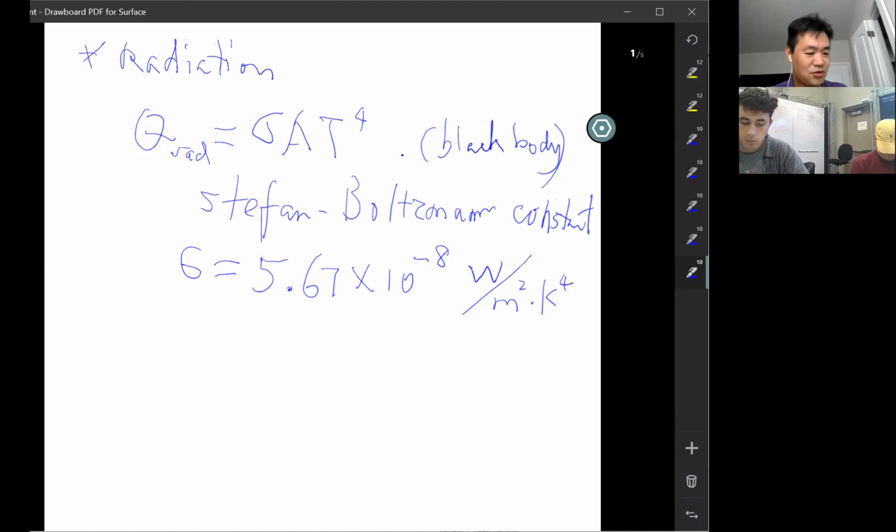But in homework problems and test problems, they always give you Celsius. If the problem has convection, radiation and conduction all together, they always give you Celsius. It's very easy to make a mistake here. When you apply the conduction and convection equations, you still use Celsius, but when you reach the radiation term, you change it to Kelvin. Very important. Remember, don't make a mistake on that.